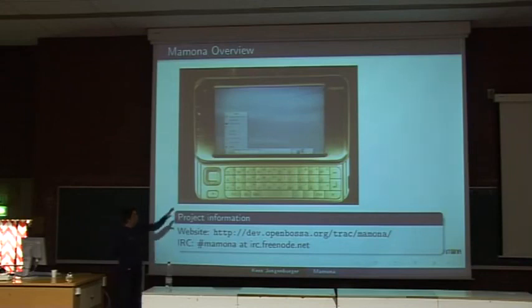Definitely, even more, I would say. Oh yeah, sorry. The question was, it's a good question, of course: can you run Mamona on a different device? And the answer is yes. Of course, it's about choices, but the choices that are made here are not that big. The big choice is we use an OMAP kernel, we use a recent GCC, and we use Enlightenment as desktop. And it's configured to have 16 bits per pixel screen depth.